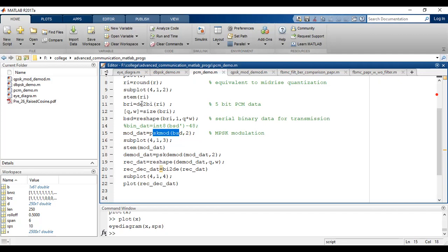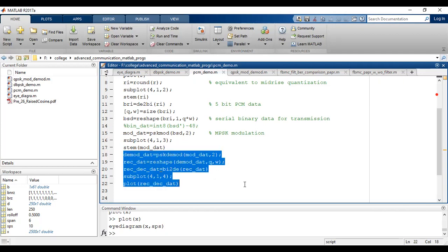Once again, once I get the data, it will be in a string. The binary data is actually a two-dimensional thing because of all the values, so I have reshaped it to get the actual one-dimensional sequence of ones and zeros. Then modulation, to indicate the steps: sampling, quantization, coding, and then modulation, something like BPSK or QPSK. Which PSK have we used, by the way? BPSK has been used symbolically, and then the reverse process. Now let us run the program.